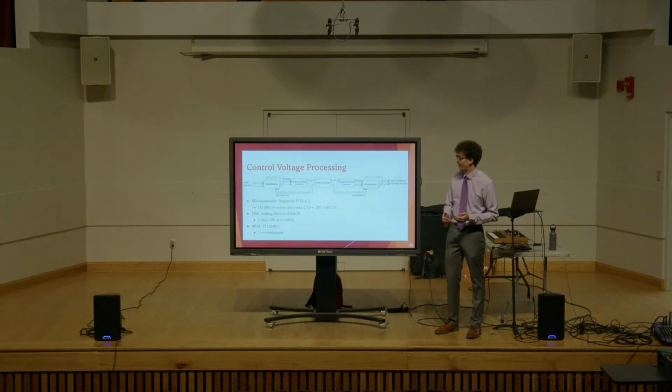And once it's done that, it will communicate that to a microcontroller in whatever communication protocol that ADC is capable of. My choice for this project is SPI, since it is probably the fastest communication protocol there is that is still reliable. And then that microcontroller, once it has that data, has to in turn give that data sequentially to a digital to analog converter.